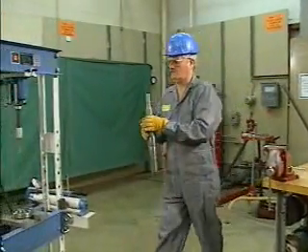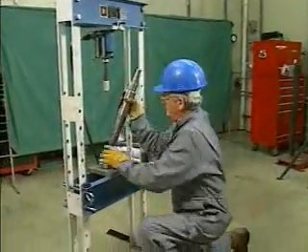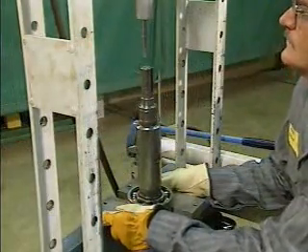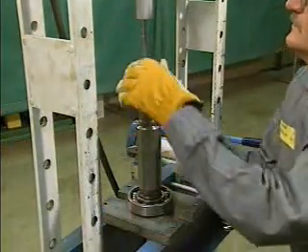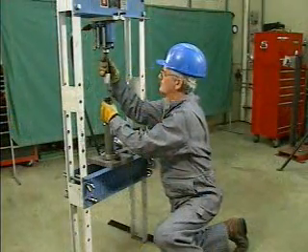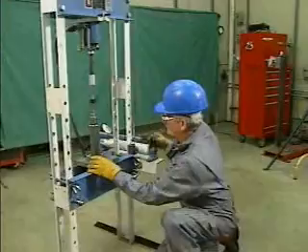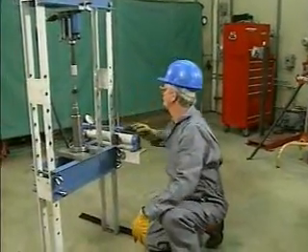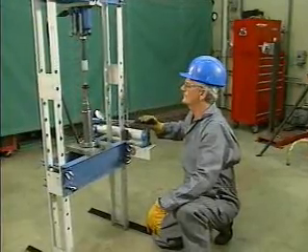Bearings are precision parts, and they must be installed as precisely as possible. How the bearing fits onto a shaft and the kind of mounting that is used are both important to the proper functioning of a bearing. The term fit refers to the tightness or looseness with which a bearing is installed onto a shaft. There are two kinds of fit: push fit and press fit.